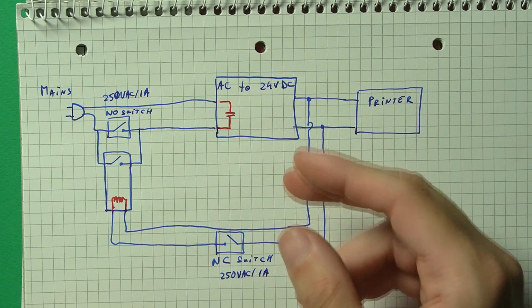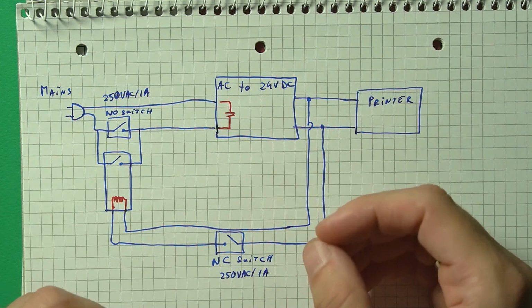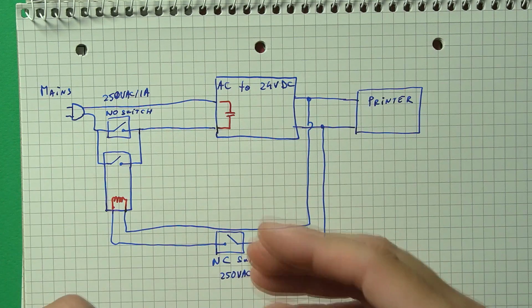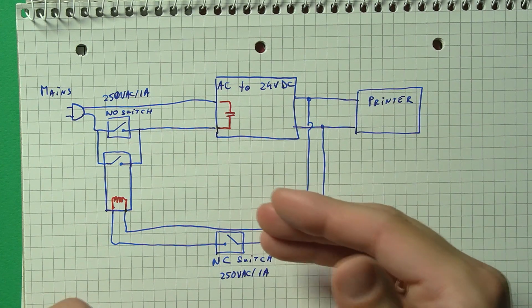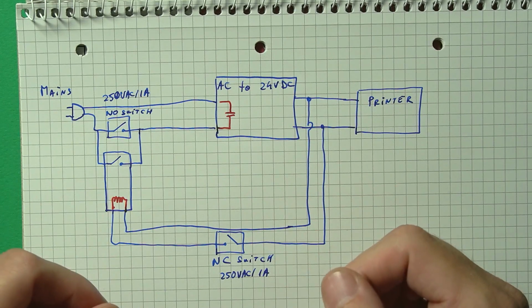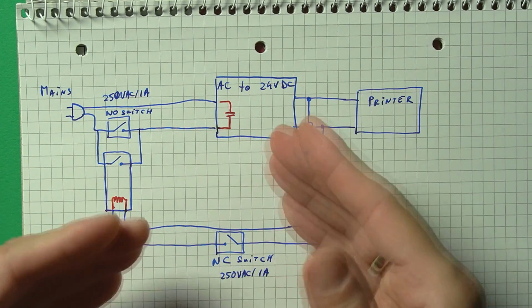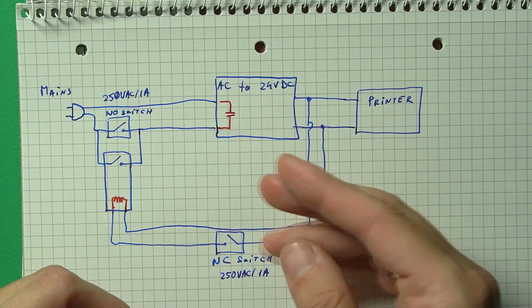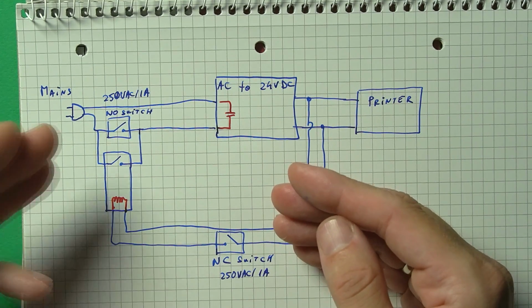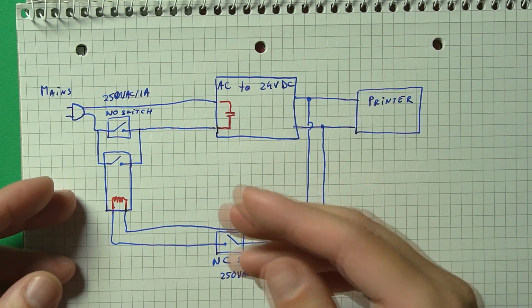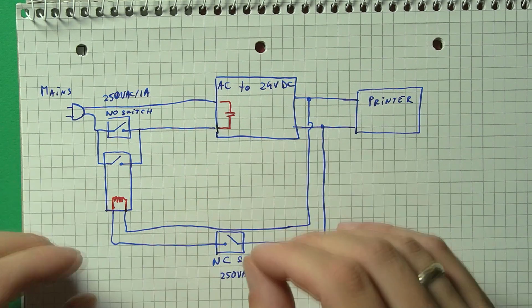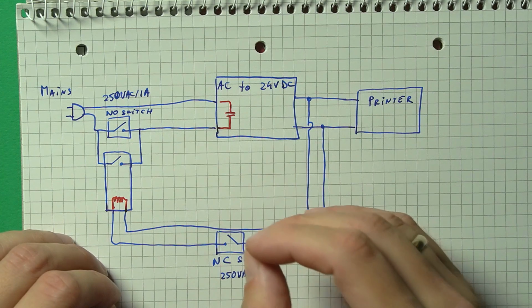The AC to DC converter is a capacitive load. The input side is a rectifying bridge with a large capacitor bank, so at turn on, you get the huge inrush current. Even though there is little to no permanent resistive load, the capacitor inrush is enough to break my low current switch. My 250 volt 1 ampere rated switch got broken during the switch closing cycle.